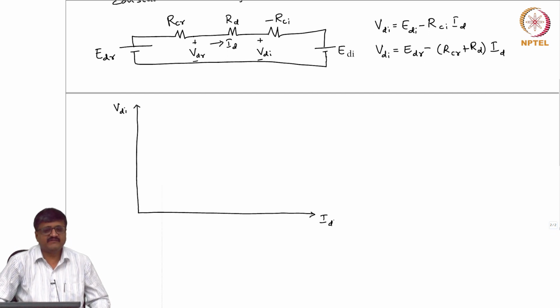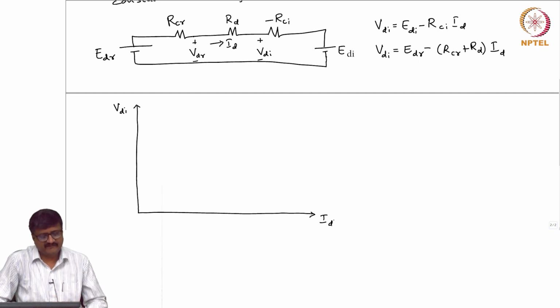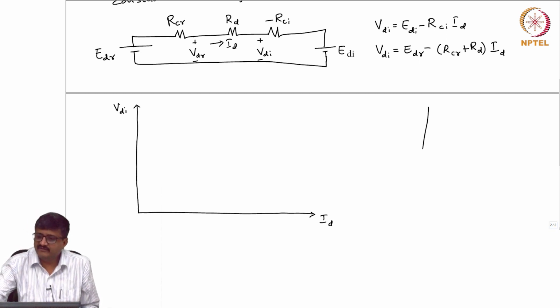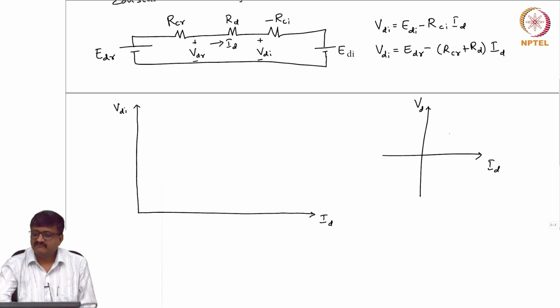See, the point is, once I decide one converter as rectifier and one converter as inverter, okay, then if you go back earlier, we considered this graph VD ID, if you recall. ID is always positive, so that means operation is possible in the first and fourth quadrant, because VD can be positive or negative depending on the converter acts as a rectifier or inverter, whereas the second and third quadrants were not allowed.